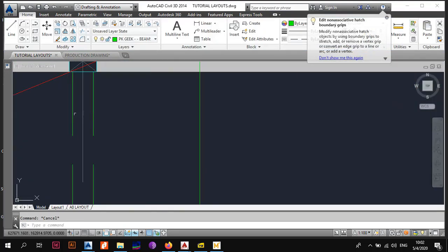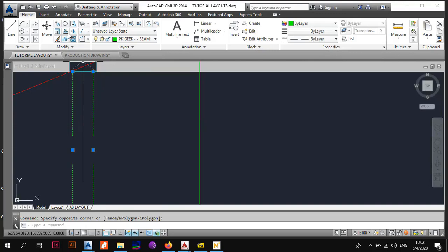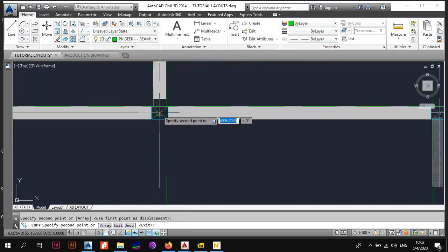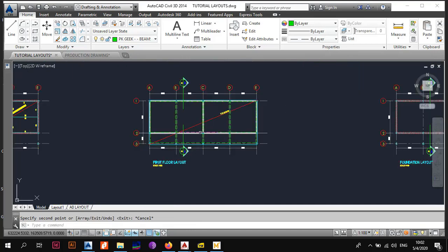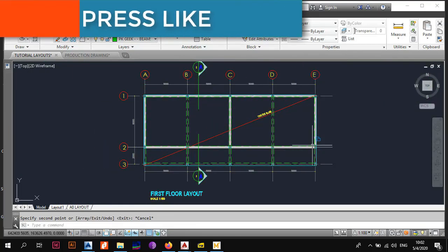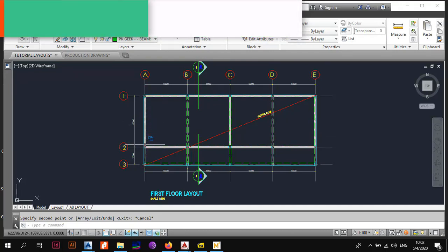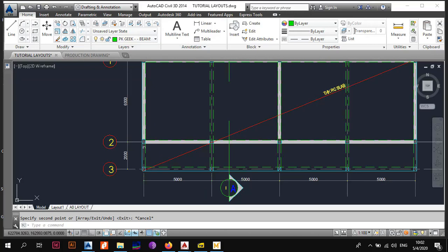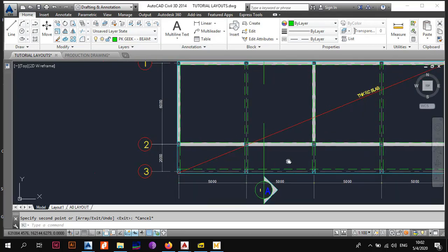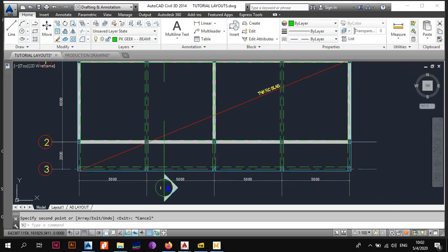So also we want to provide beams over there, so just copy this from the center and place it there as well. So now you have a beam on this wall, a beam on top of this wall, and a beam on top of this wall. This is essentially one beam, on top of this wall for this section, and then it goes all the way to the other column for 2 meters. Same applies throughout the entire balcony.